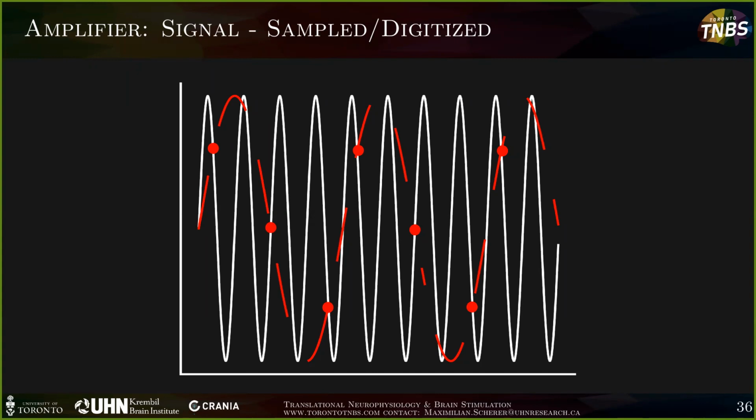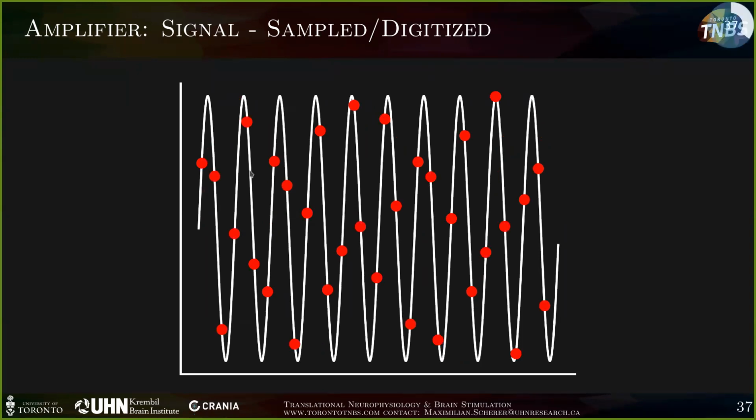And by increasing those data points to a higher count, you're basically changing the possibility of me fitting a bad sine to your data. Because if you have a high enough number of data points, to be more precise, more than 2 times the highest frequency in your signal, you're basically leaving me with only the option of fitting a sine to those data points that exactly fits your data.